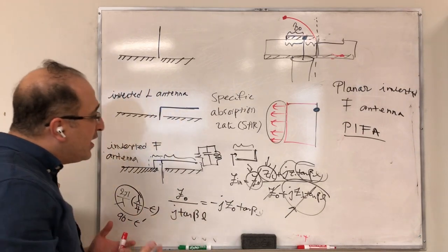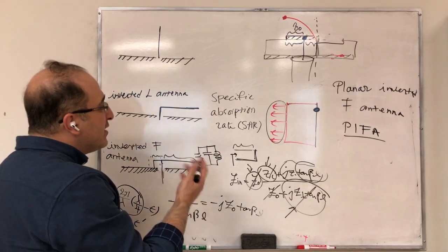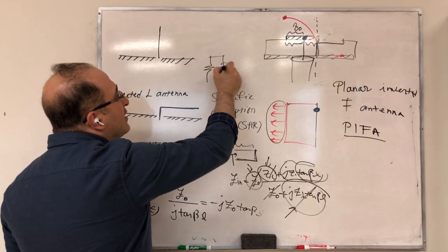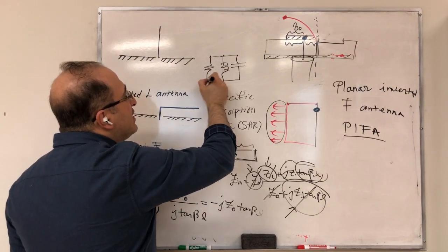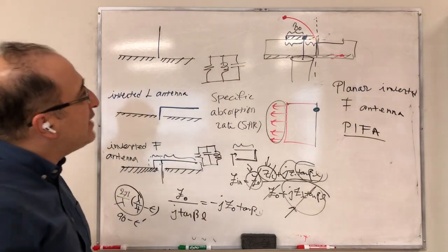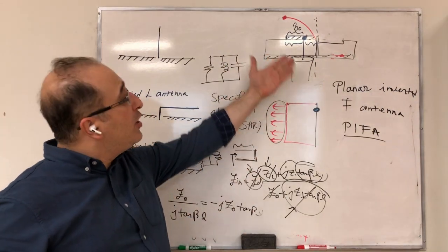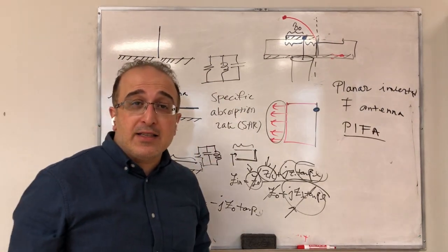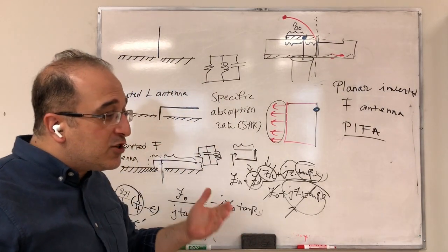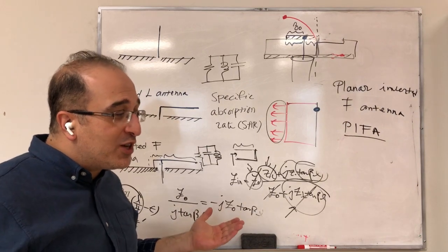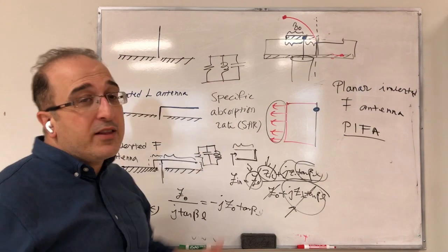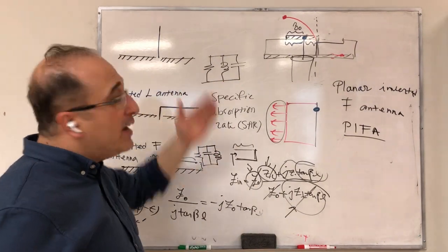And finally, remember that in circuit courses, we talk so much about RLC. And this is nice because we can understand that a complicated structure like a patch antenna can be modeled by an RLC circuit, because essentially we can think of it from a transmission line point of view, and from one side it might be an inductor, from another side it can be a capacitor.